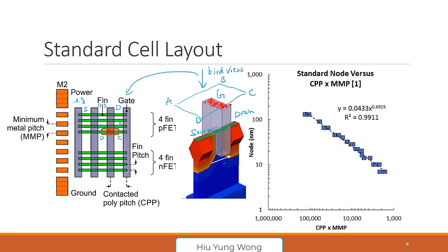So in our class, we are not going to teach this layout. So probably this is only one or maybe a few that you will see, but you can appreciate why it is important for density. But in reality, after fabrication, you get the one on the right. Okay. And now here, just to emphasize again, CPP is important. And that is how it has been scaling, even up to 7 nanometer technology. It is still following this rule.